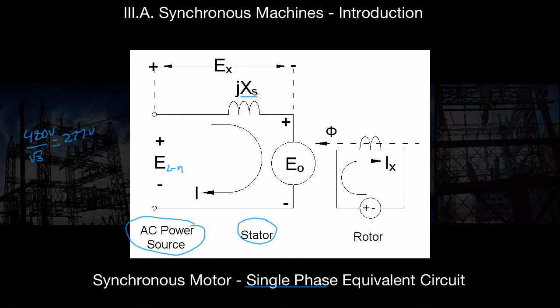And our synchronous reactance is still the reactance, or the imaginary component, of the impedance of our stator coils. And now look at this. We still have a rotor inducing voltage, right? Well, the reason is on a synchronous motor, we're still inducing a voltage.